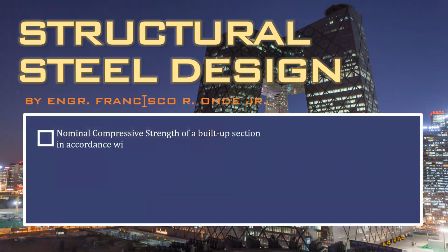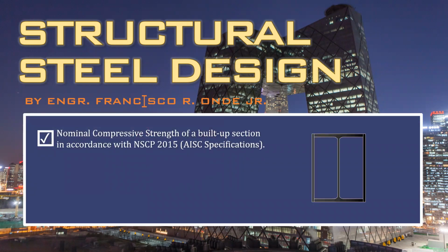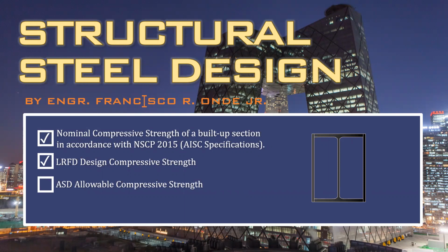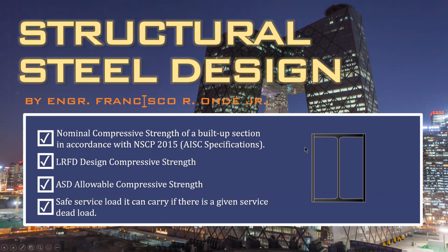In this video we'll be discussing how to calculate the nominal compressive strength of a built-up section in accordance with the NSCP 2015 specification, which is the same as the AISC specifications. This is the built-up section that we're going to discuss. We'll also be discussing the LRFD design compressive strength of the section and the ASD allowable compressive strength, considering flexural buckling only. After getting those strengths, we're going to calculate the safe service load the column can carry if there is a given service dead load.